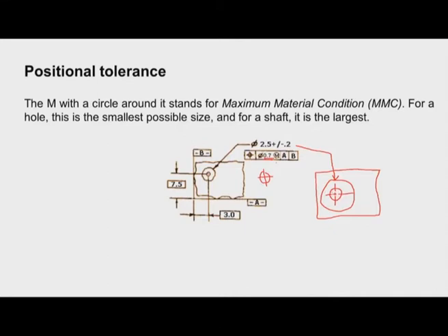That means the center of the hole can lie anywhere within a 0.7 millimeter diameter, satisfying this maximum material condition.